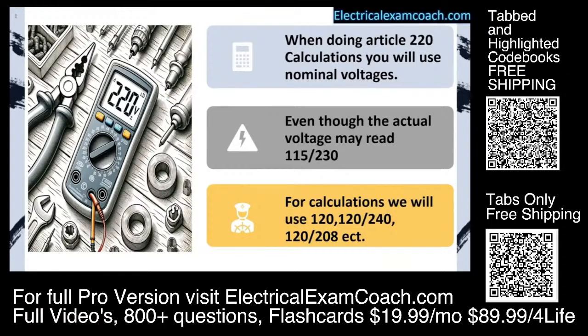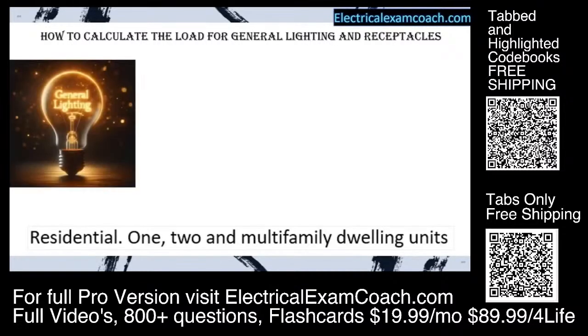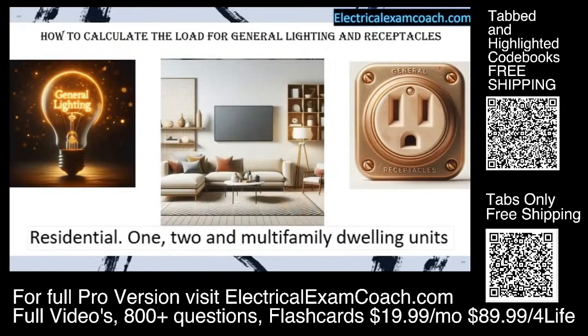The first thing that we're going to learn about for our whole home load calculation is how to calculate the general lighting and receptacle loads. This is going to cover all of our general lighting and general receptacles in places like bedrooms, living rooms, hallways, everywhere that's considered a general area. We've grouped all of them together and come up with a very easy way to do it. Now, what I'm getting ready to teach you only applies to residential one-, two-, and multifamily dwelling units.